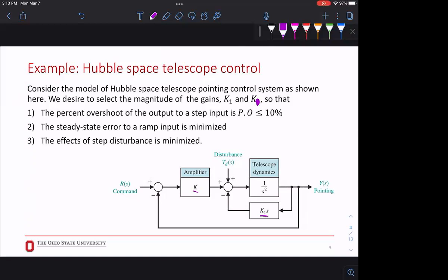Sometimes your conditions are such that they are independent and you can say, okay, I'm going to solve for percent overshoot, then I'm going to solve for zeta, the damping ratio, then I'm going to solve for time, like T of S or whatever, right? Sometimes they're independent, but usually for designing a controller, like picking gain, you need to consider both of them because both K's, for example, will show up. You find a relationship. You don't find an exact number like in CP18. There was a relationship in there. So be ready to find a relationship and be ready to solve all of them together.